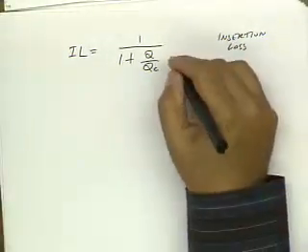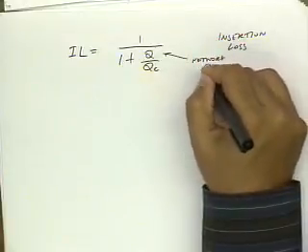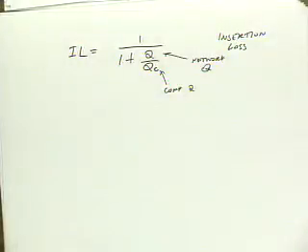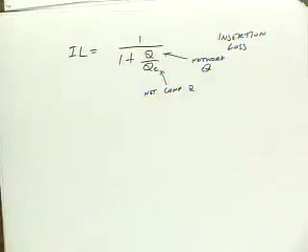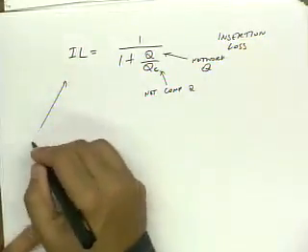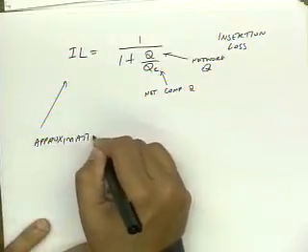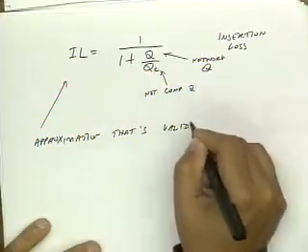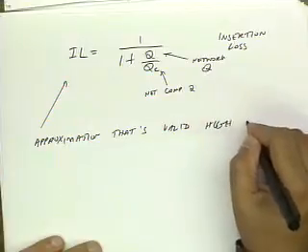Okay, so this is the network Q. This is the component Q. It's the net component Q because we're using both inductors and capacitors. Okay, now this is an approximation, and it's more and more valid as we go to a high Q circuit.